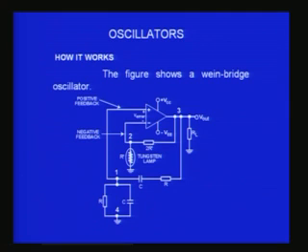So now you also normally have here the resistance which is connected to the inverting input. You do not use normal resistor, you use a tungsten lamp, a small lamp you can put. Why do you put the tungsten lamp? Because the tungsten lamp, when the resistance is there, it is not for glowing, the bulb will not glow at all for the low current that we are going to send,